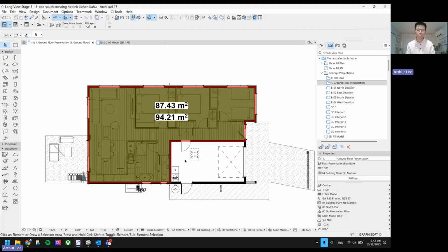So in this case, for example, I know the stud height is 2.4, probably 2.45 in reality. And then the thickness of the roof insulation is 280, or I can round it up to 300. And if I use a typical rib raft, the thickness of the slab is also 300. So to simplify things, especially in this conceptual stage, in the early stage of the project, I'm just going to assume my wall height measured to the external corner is exactly 3 meters.